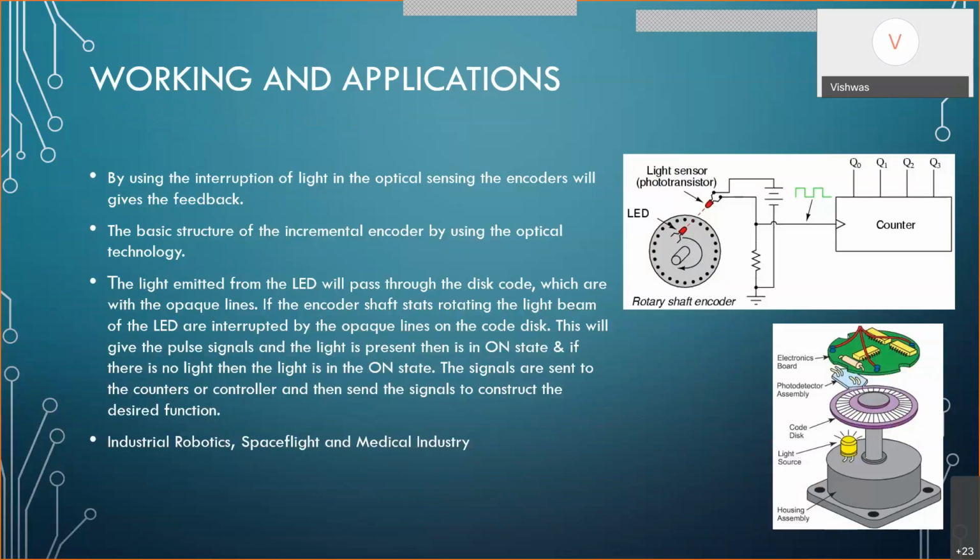Here you can see in the first image a rotary encoder which has an LED and phototransistor system. There are black dots and no dots on the circle. Whenever there is a black dot, it produces a hindrance on the intensity of the light being put on the phototransistor. So the amplitude will be a little bit lesser in that case, and we mark it as 0. For the normal one, we can mark it as 1.